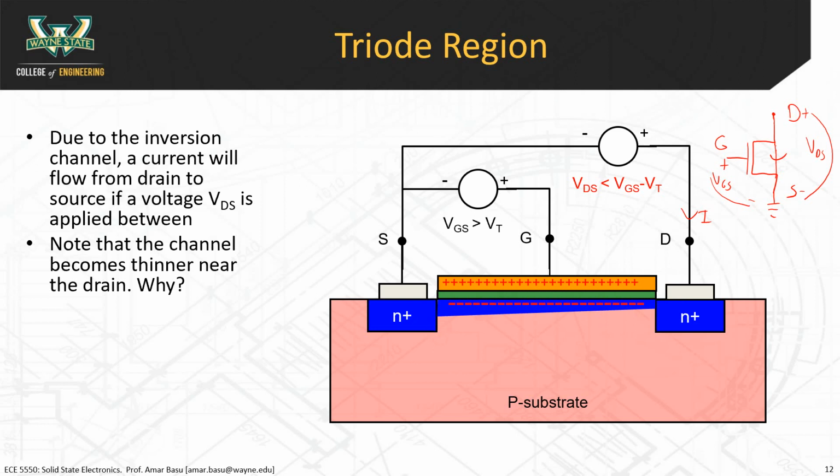Do electrons recombine as they travel through the P substrate? That is an excellent probability. That's not the reason why this happens, but recombination through the N channel, that's a really interesting thought. I think what would probably happen is that as the electrons are traveling through here, since this is an N-type material and there's very few holes there, there's less chance at recombination.